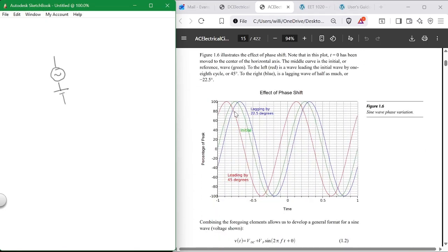Now, why would DC offsets be bad? Because they could give you a bad signal. Most computer boards, I've told you this before, have capacitors on their inputs for signals because they strip off that DC offset. The capacitor will strip that off.